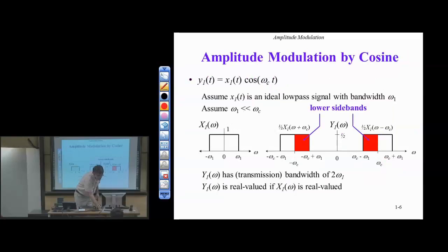All right, so now we've got a better handle on bandwidth and a formal definition to work with, which is extent in positive frequencies. Let's now talk in more detail about up conversion, which we talked about in lecture 0 slides. One way to perform up conversion is to multiply by a cosine of fixed frequency. This cosine has a fixed frequency of omega c, which is in radians per second. And this is 2 pi times fc.